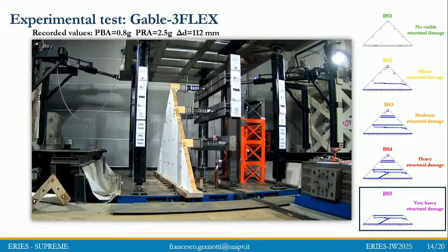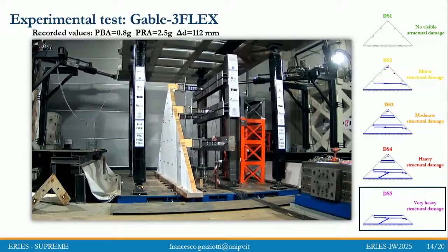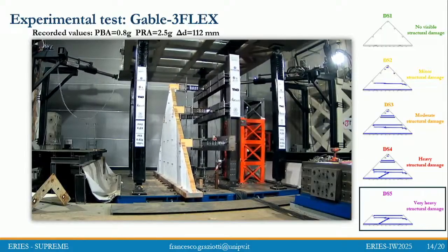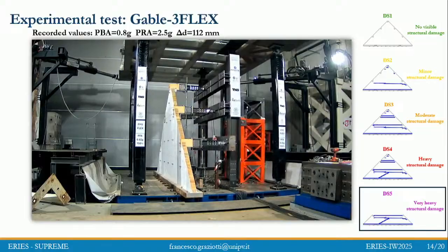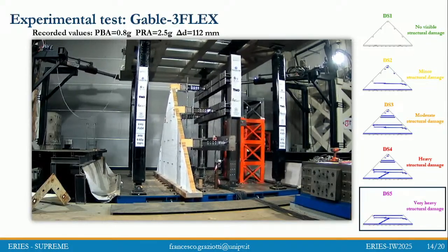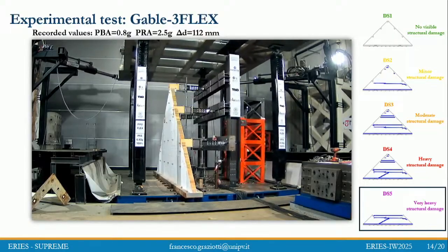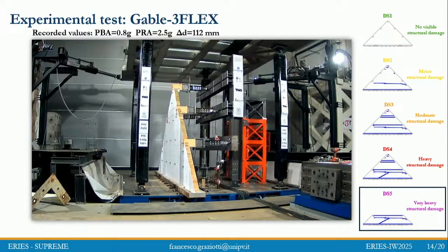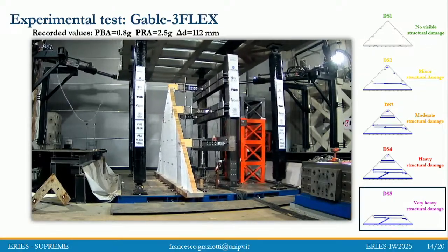The third one was the one that we were more curious about, the one with a completely different acceleration top and bottom. You really see how the top shake table is accelerating a lot. In this case, we reached 2.5 g on the top one. And as expected, also in this case, the base acceleration at collapse was lower than before.